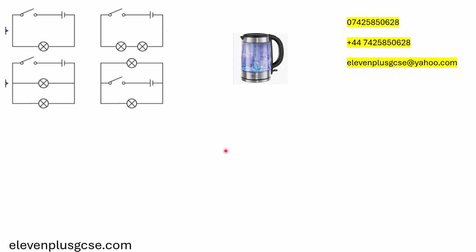All right. Now, the other thing that I want to explain is something called power. So this appliance at the bottom will have what we call power. Now, power is given by volts times current in electricity. So V times I. At the bottom, there'll be something written like, for example, 200 watts. Now, 200 watts means this: every second, if this thing is working efficiently, it's taking 200 joules of energy from the socket to the water. That's what it means. All right.